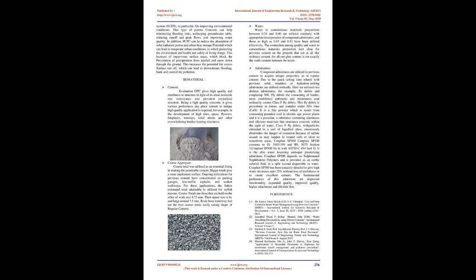The voids are created in the concrete for passing water through it, also reducing the problem of water logging, making the road surface skid resistant, and increasing the water table. The performance of pervious concrete was compared with the material used for the construction of concrete road pavements. Tests were conducted to determine properties of concrete like compressive strength, flexural strength, and also permeability. It was found that pervious concrete pavements possess some positive features like increased skid resistance and high permeability, but most importantly it requires high strength for highly trafficked areas.